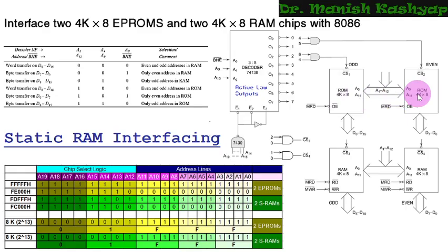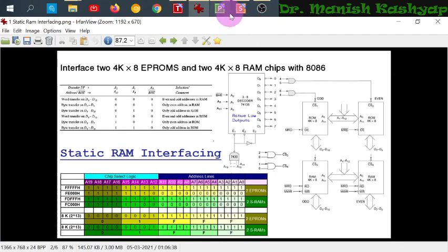So now how to accommodate this, right? I said that 13 address lines will be required, and that is why we will require A0 to A12, that is, all these locations. But if you see the individual chip, then only 12 address lines are required. So this is fair. This is okay. Why is this okay? Now let me tell you the reason for this.